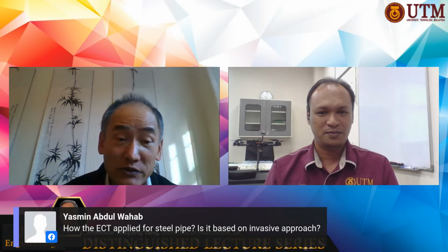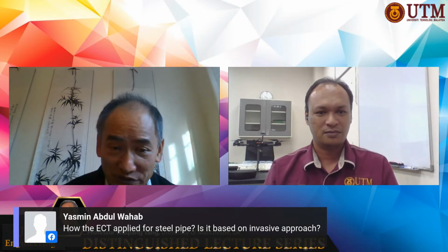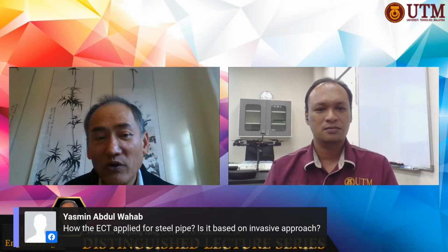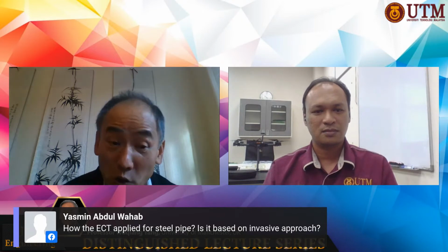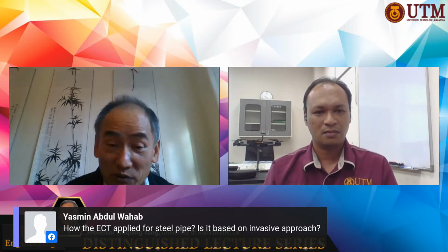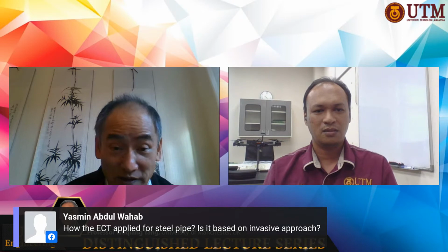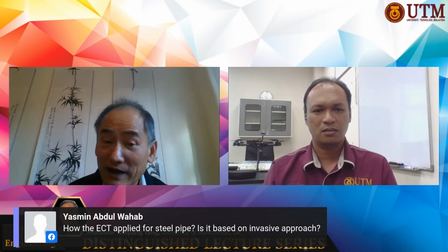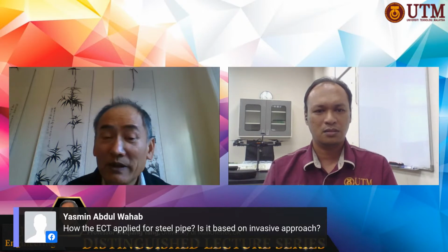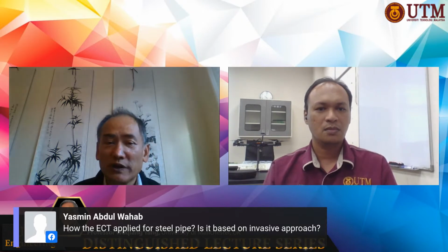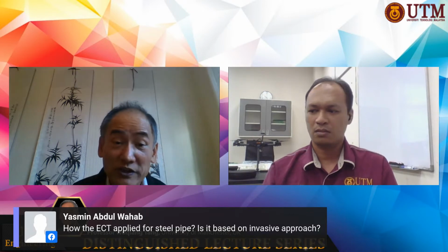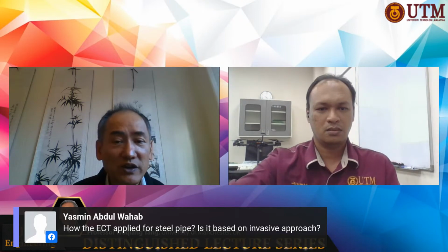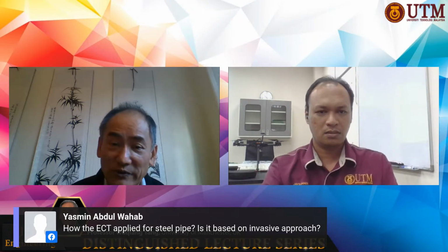When I showed you two extreme sensors, one is for the oil industry, one is for a clean coal application. Those two sensors are actually steel because of high pressure, high temperature. In particular, high pressure needs steel. But with steel, we have to use an internal insulation layer, such as PEEK, which is a good material.